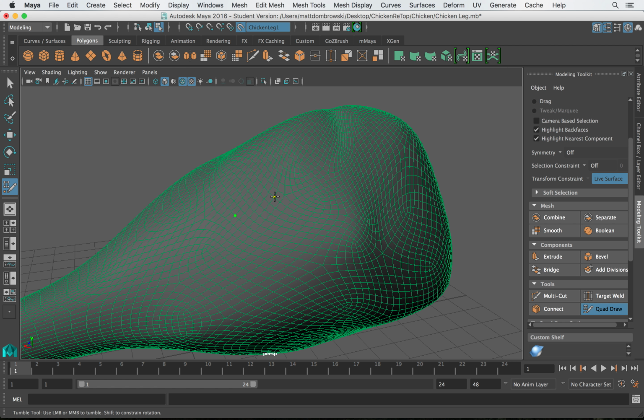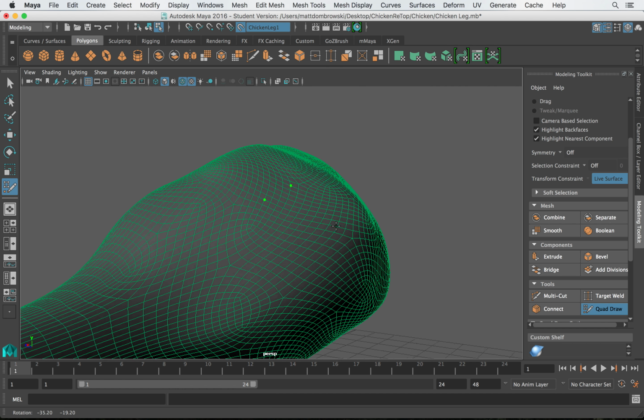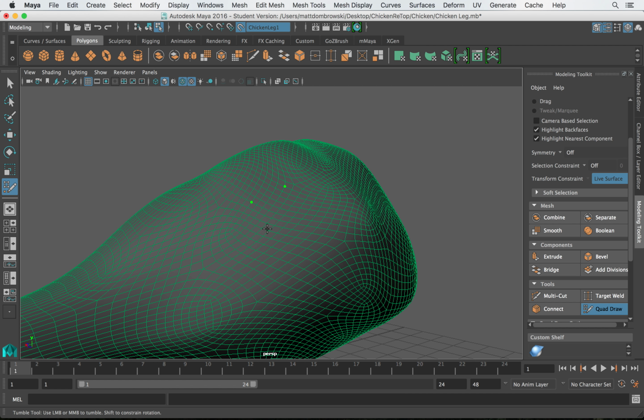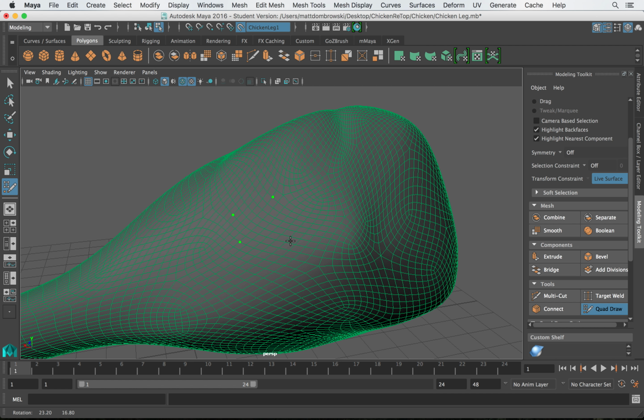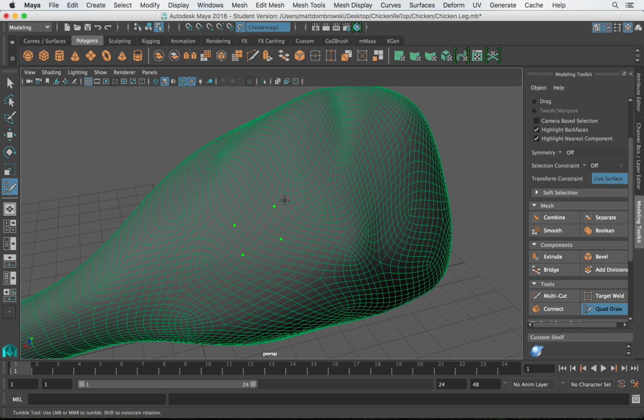I'm going to go ahead and create another dot. You can see the same thing, and maybe a third dot, and a fourth dot. Now, when I get 4 dots, we know four vertices could equal a face, and I hold my shift key down and hover over or in between those dots, I get a face. Now here's the trick.